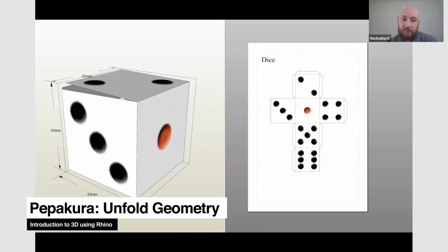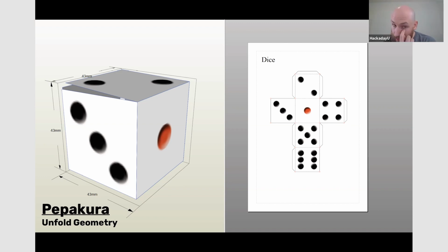So another fantastic software is Pepakura. It's less than $40 to buy, and you can drag any 3D model from Rhino. And I used a .stl file, which wouldn't transfer over textures, but it just unfolds the geometry and gives you a very precise thing to cut with flaps, so that you can cut it out and assemble it as a sort of paper model.